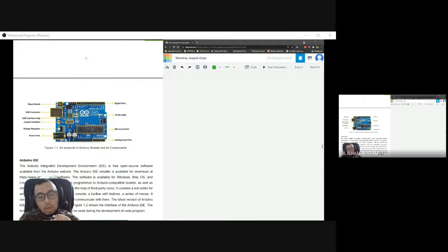And the pins you'll be using to control a motor or to move anything are the digital pins. This is the important pin that you will play with a lot. If you see the digital pins in the picture, at the bottom there are 0 and 1, TX and RX. That is what we call serial communication devices. So typically we connect an LCD or maybe wireless transmission via here. And in the picture, there are also pins 11, 10, 9, 6, 5 and 3.